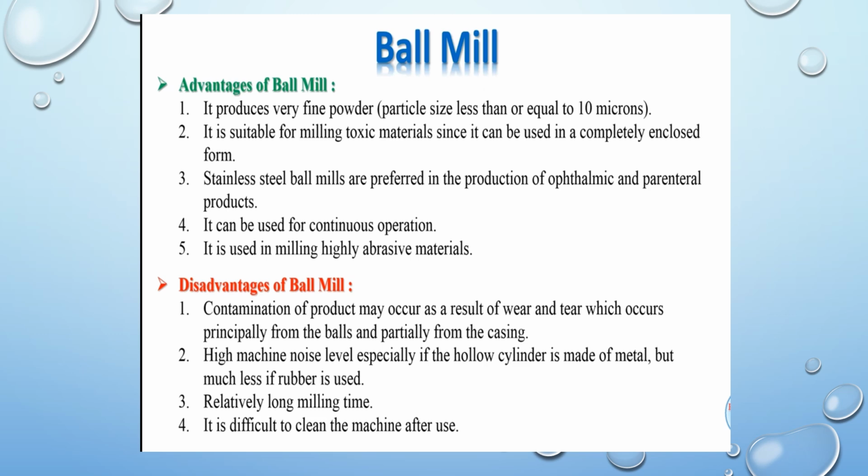The selection of materials of the balls plays an important role. Generally, a harder material will be selected to synthesize softer materials. For example, alpha alumina and zirconia are used widely as balls for synthesizing nanomaterials in view of their high grinding resistance values.